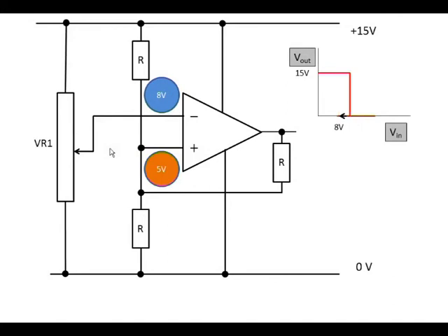In fact, we have to lower the voltage right back to 5 volts until we have a voltage which is sufficient to cause the output to swing back to 15. And as it does that, you can see how the threshold voltage at the non-inverting input has changed back to 10 volts. When we go back to 2 volts and eventually back to 0 volts, you can see that the output of the circuit stays at 15 volts.